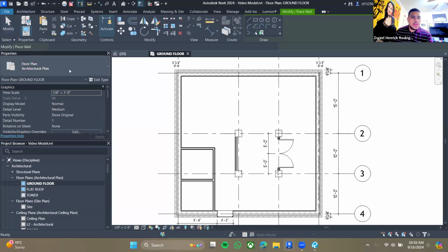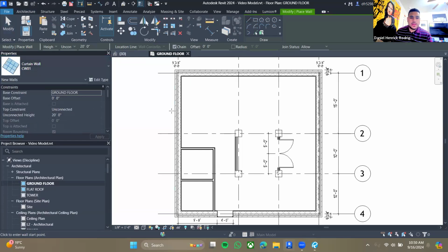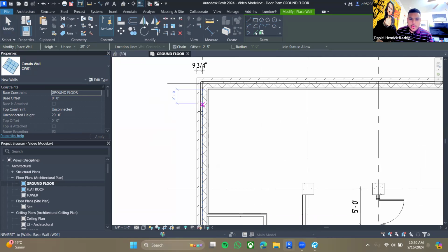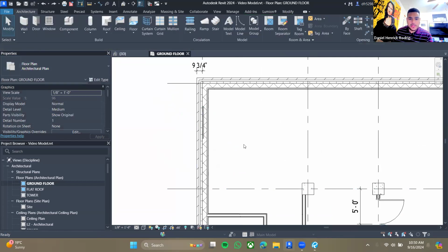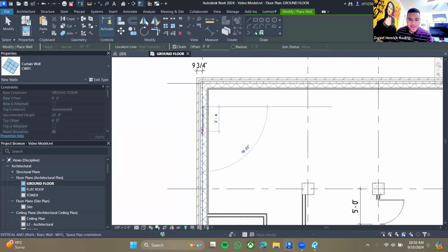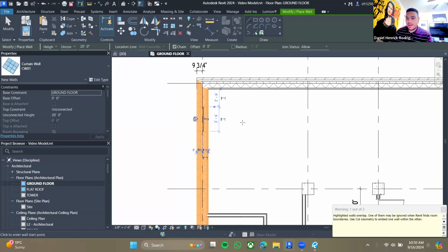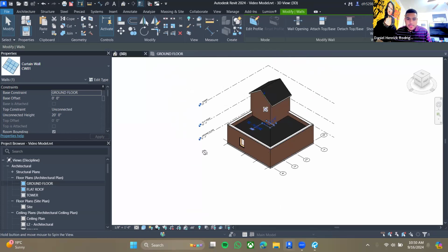And we're going to click on Wall. And you guys should create a wall that has a name. I already have it here, CW1, right? You're just going to go to the center of the wall and place it wherever here. And you're going to notice that, sorry, I click off of things so quick that I'm just used to Revit complaining and me ignoring it immediately. But I know that a lot of people, when they're first working with it, think, oh no, Revit didn't like it, so it must be wrong. No, this is just telling us that the walls overlap. And like it says here, it can be ignored, so it's not going to break the program, but it's just letting you know that, hey, these things are occupying the same space, right?